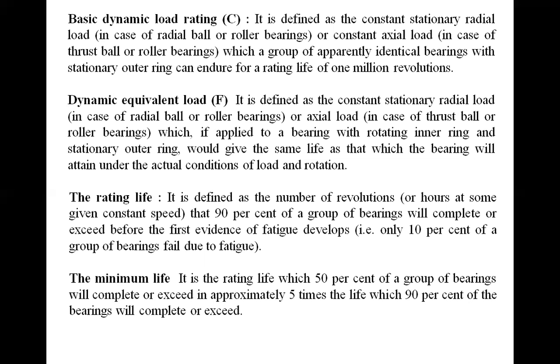The bearing life is taken by the actual practical approach, because we have to think about practically how many bearings complete, and what percent of life. Failure of only 10% is important. If 10% of the bearings fail, then we say that is the rated life for that particular speed and for that particular load. Okay.